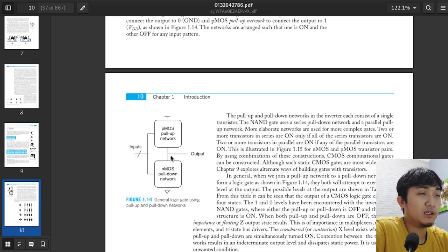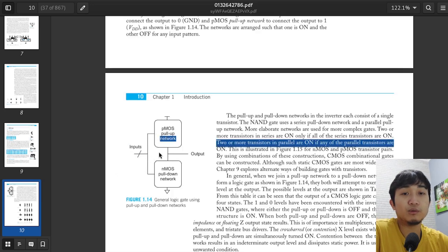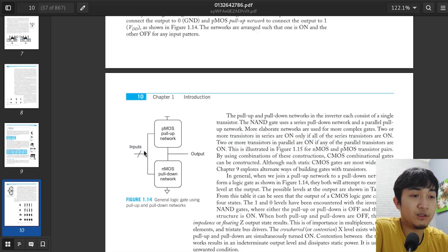The transistor gates act as an input, and here we can have a high impedance input, which doesn't require much current to drive, and the output can be low resistance, which is good because we want the output to be able to drive many logic gates down the line, which we usually call fan out.